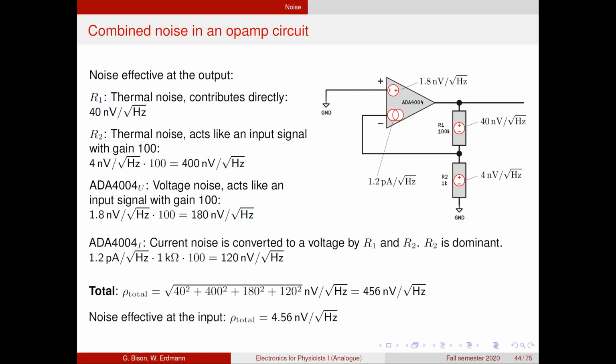So this is a trade-off that you have to live with. If you build a fundamental physics experiment where power doesn't matter, then you can, of course, go to the smallest resistors that are still practical given the output current capability of your amplifier. If you have to build 1 million of those in really small space, then power might be a concern, and then you have to optimize for power as well. And if you are an application engineer and you want to build something that is battery operated, then going to the smallest resistor values is also not an option.